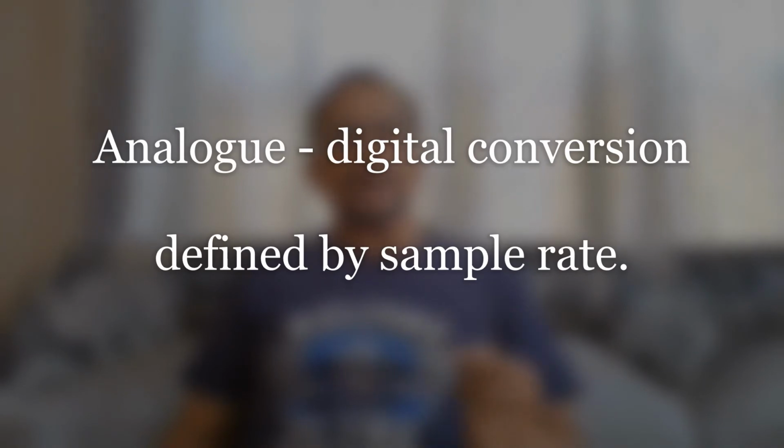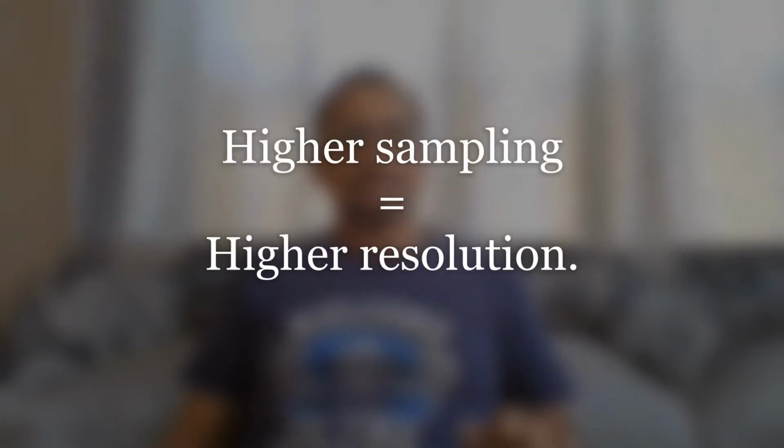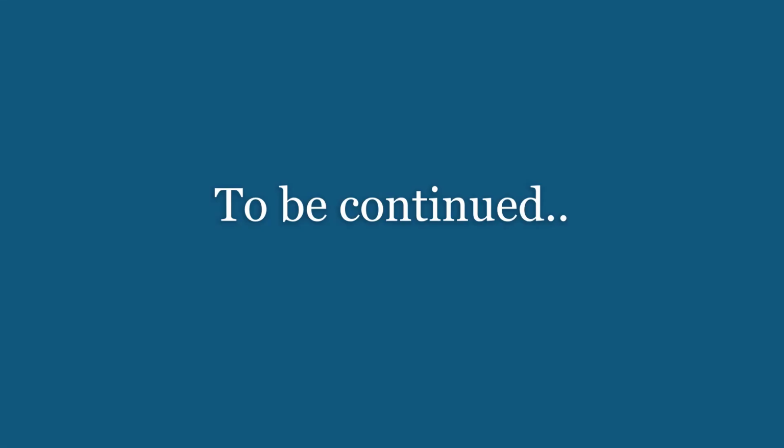Now, for data transmission, there is an analog to digital conversion. The voltage generated for each channel is digitized. These digital signal characteristics are defined by the analog to digital conversion sample rate. Reson 8000 series uses 8-bit sampling, while the Reson 7000 series uses 12-bit quadrature sampling and has a sample rate of 34 kHz. So, for data acquired on the same seabed with the same ping rate, quite obviously 12-bit quadrature sampling will provide a better resolution than 8-bit sampling.